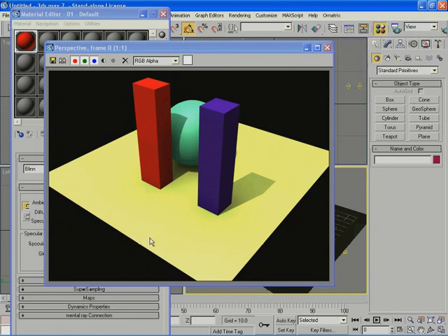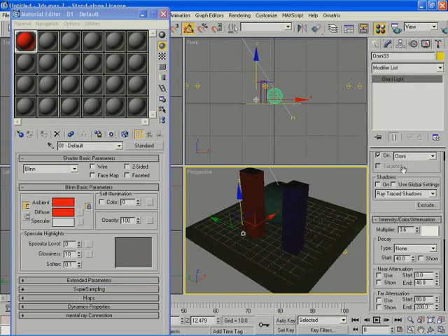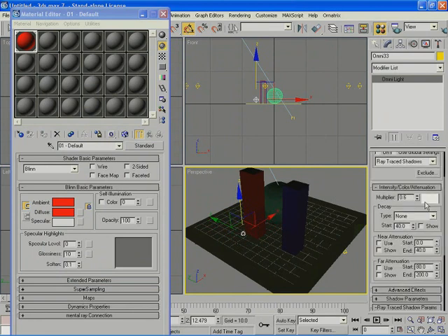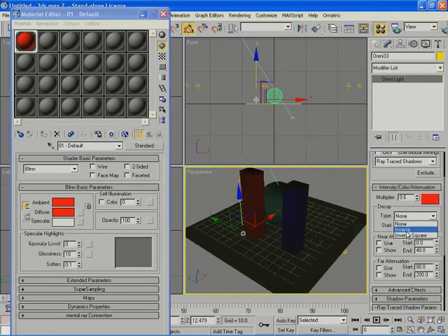So in case you want to get it here, in this example, you have to fake it. So we'd have to create an omni-light right in front of it, and I would make it reddish, so I can grab this color here and drag it to my multiplier or my light color, choose copy, and I would give it a decay so that it only affects this area, and lower down the multiplier and render. So here I'll be simulating a color bleed effect.